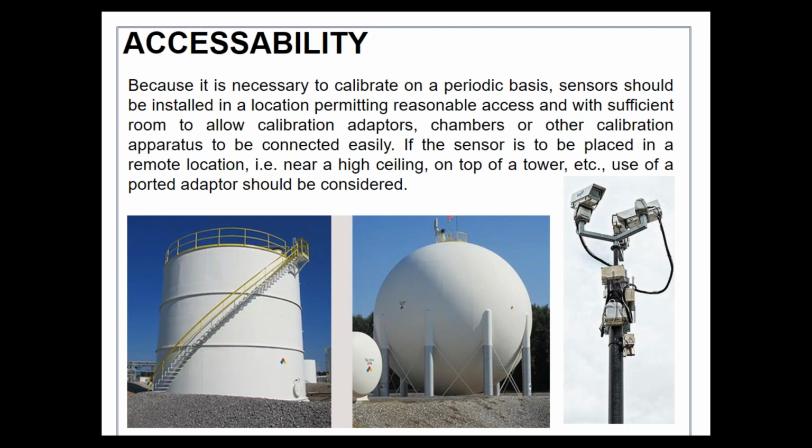Whereas now, with a device such as the gas cell, you can put the sensor at the top of the pole, put the XMO at floor level, and put a tube that runs up to the sensor with a ported adapter, and now you do all your calibration and gas testing from floor level. So we have accessories that make it easier, but you need to know the right place to put a sensor to make everybody's job easier.